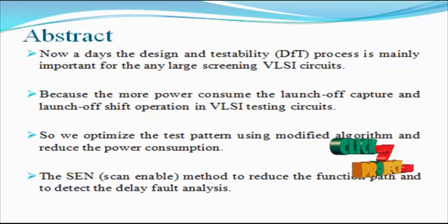On the other hand, such patterns increase the switching activity during the launch and capture operation. Patterns optimized for quality and cost may end up violating peak power constraints, resulting in yield loss, while pattern generation under low switching activity constraints may lead to loss in test quality and/or pattern count inflation.